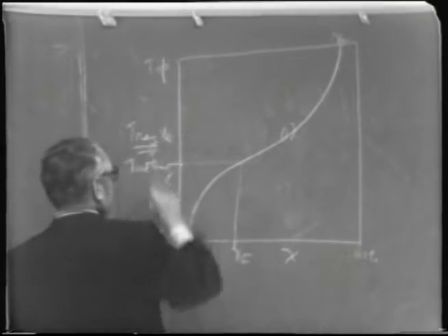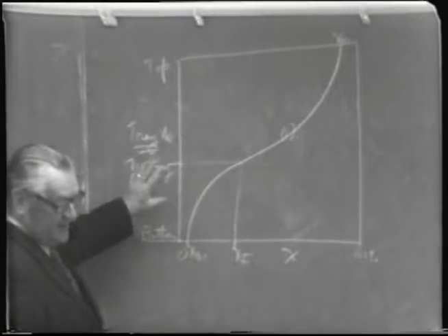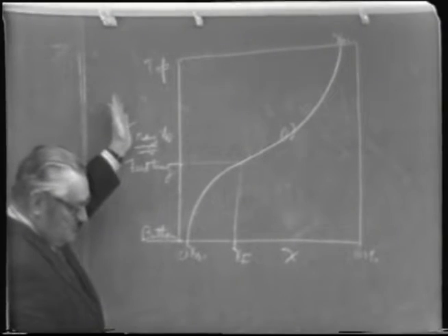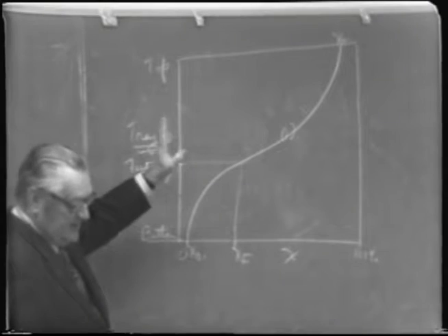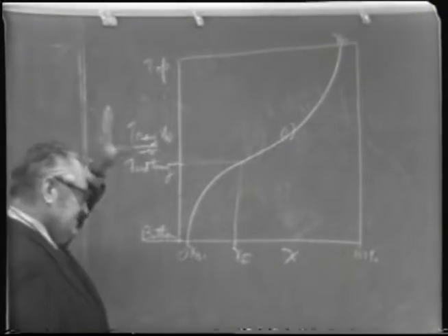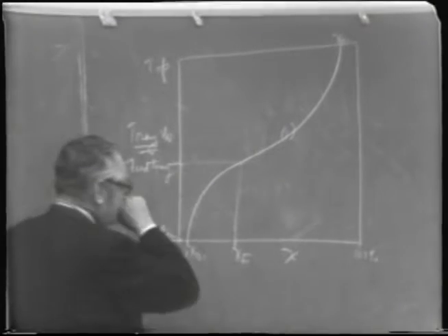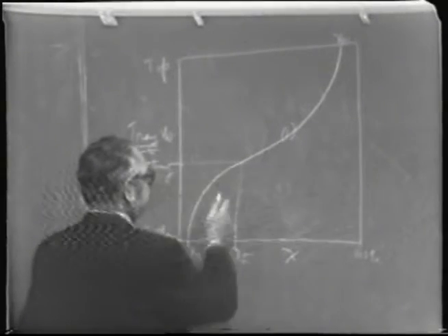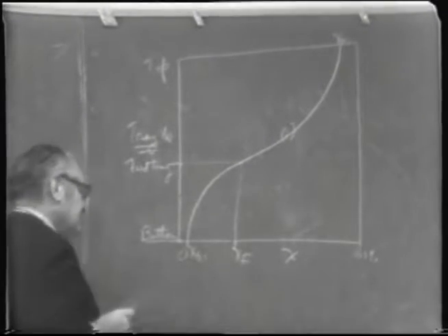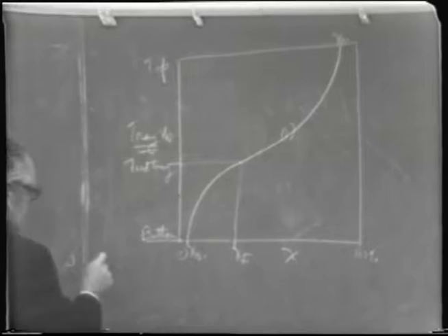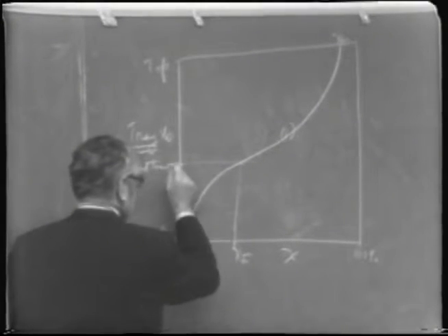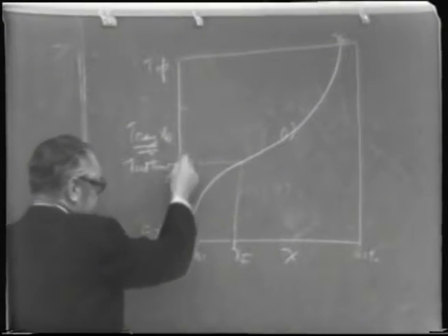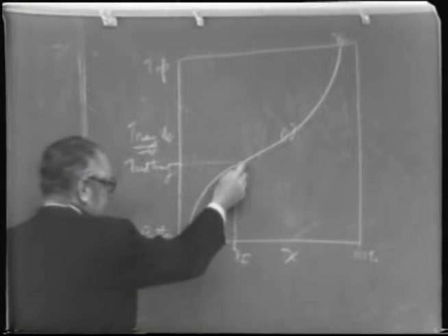This is the actual number of trays. We can call it ideal trays, it doesn't make any difference for the purpose here. In other words, this would be the case where the feed tray has the same composition as the overflow from the tray above mixing with the feed.